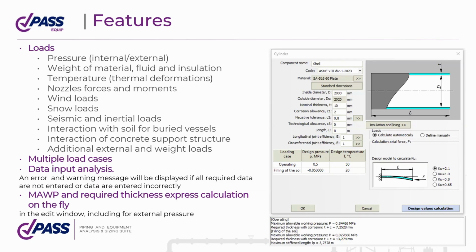And we also can do buried vessels. And for these underground vessels, we, of course, take into account interaction with soil weight, and interaction with concrete support structure. And you can also apply some additional external and weight loads. And you can do multiple load cases. You can define several load cases like operation, transportation, testing, and so on, and do this calculation simultaneously for all load cases.